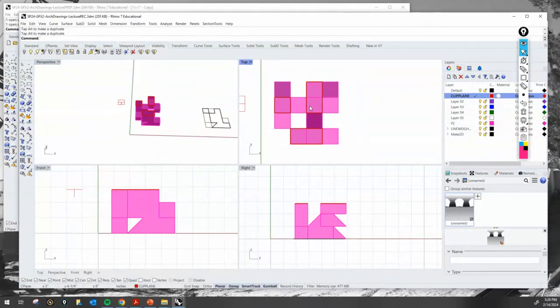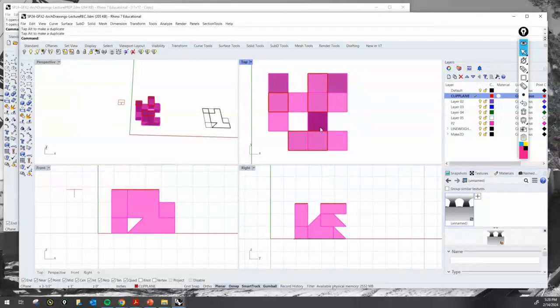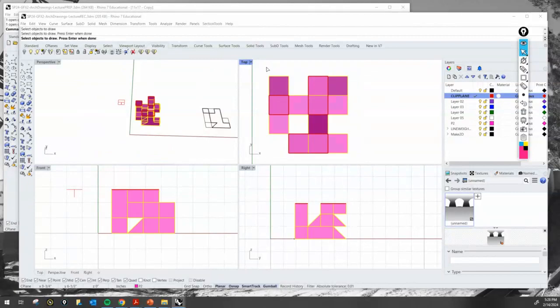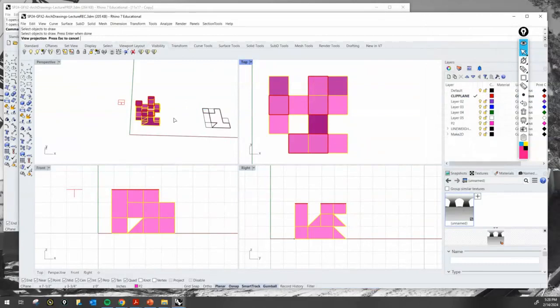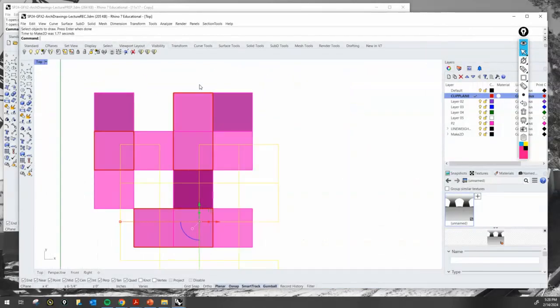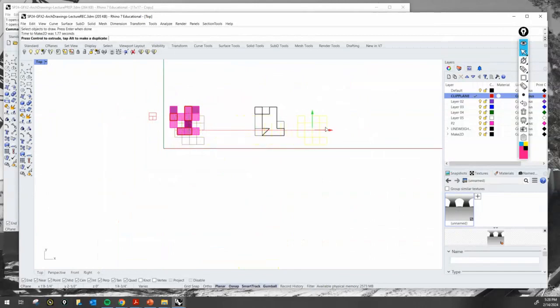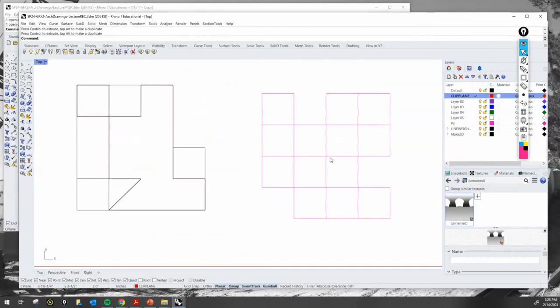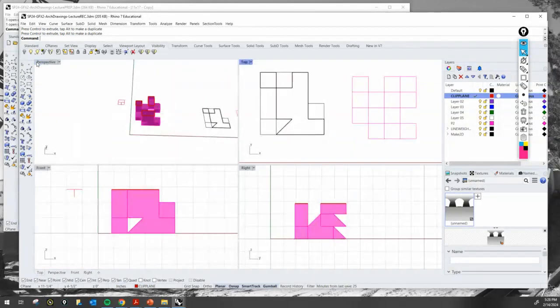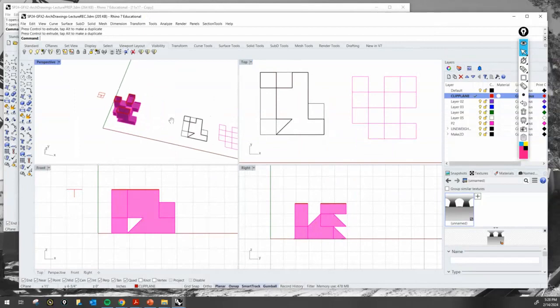And the way that we can do that is if we go to the top view and we repeat the operation. We type make 2D, enter, select these objects right here, enter. You can leave the settings as you see on my screen right here, click OK. And again, go to your top view right away, move this out of the way over here, and bring it over here. You should end up with a section cut, but not really.